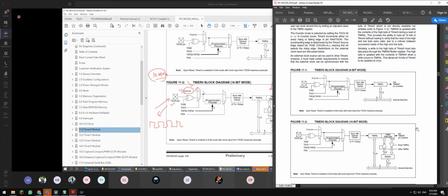So then we come into here. Let's say we choose this, we come into here. This is a prescaler. Prescaler is basically just to reduce the frequency. Let's say for example I'm using 10 megahertz divided by 4. I hope there's a paper with you. So it's equivalent to 2.5 megahertz.